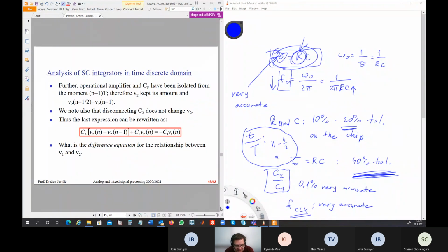At the end, you have this difference equation. So this is the most important. If you can derive it at home, then it will be good. You can look at the books. I will show you where, and then you probably can come to this. This is called a difference equation, and this difference equation is solved using the Z transform. So this is from discrete time system analysis.